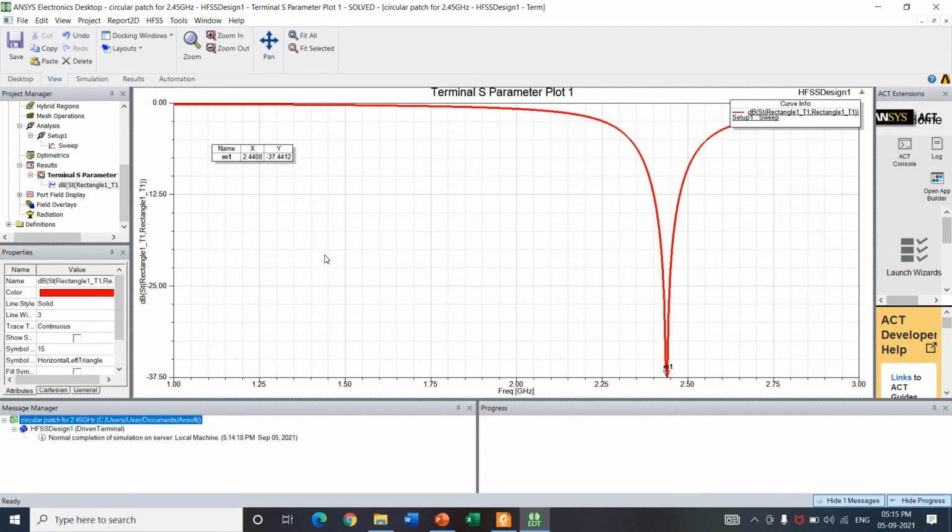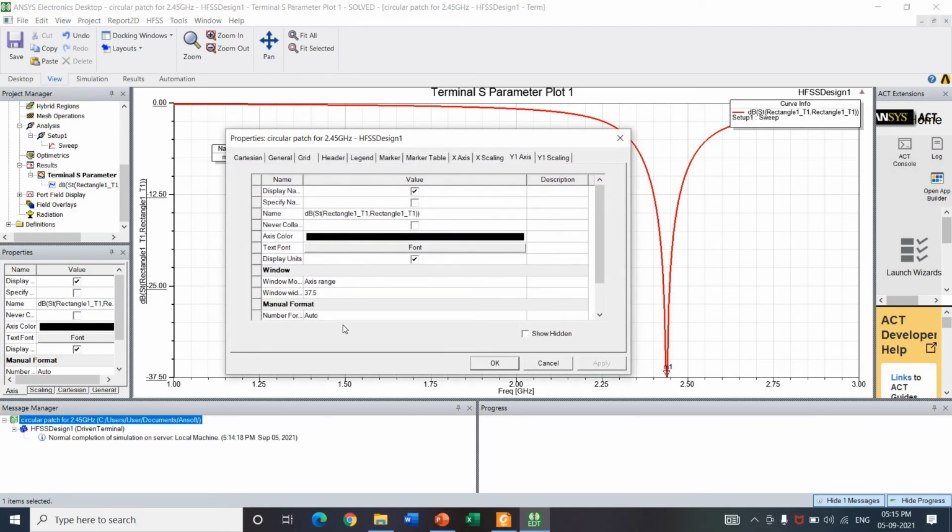take the bandwidth of the antenna. So here, as we have studied in the gain plot and all, you will get a plot in this way. So from the maximum you will take minus 3 dB. Okay. Here we will take minus 10 dB as a reference, that is the tolerance we have considered. So this minus 10 dB, when I draw a line in this particular place, you should get two lines. I will draw it here. Before that, I will do some modifications in these values.